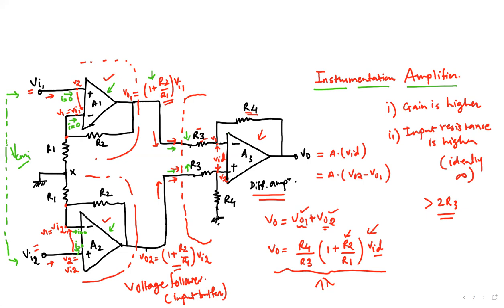That has to be the case, but now the differential amplifier will have a larger common mode signal here, because the common mode signal comes directly from the amplified first stage. They are not getting cancelled at the first stage. So the differential amplifier will have a higher common mode gain as well as a differential gain in the combined output. We have to take this into consideration.